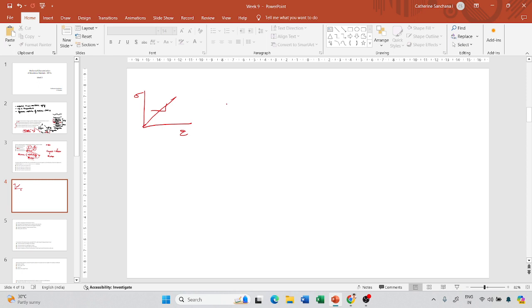It is more or less like measuring the modulus of an elastic material. Say I am having a steel rod and I am measuring its modulus. So E is my modulus. What is the formula for E? Young's modulus is equal to stress by strain. As long as the material response is linear, if I keep varying the strain, my modulus is not going to vary, because my stress will also vary correspondingly, such that the stress to strain ratio is maintained. That is, my modulus remains constant.